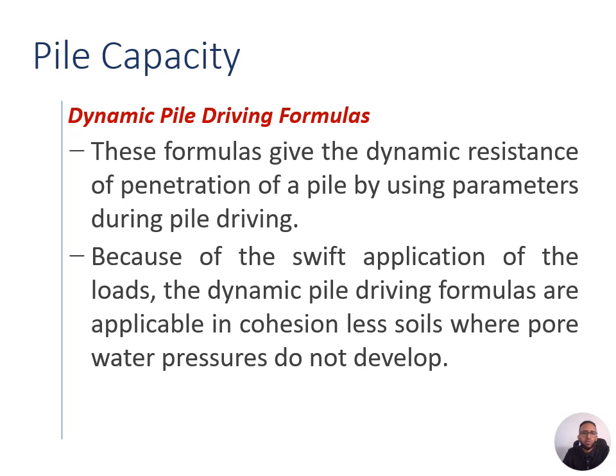The key advantage of dynamic formula is rapid application of loads, which makes them suitable for cohesionless soils where pore water pressure do not have time to develop. The formula takes into account factors such as hammer energy, pile weight, and the distance the pile is driven per blow to calculate the ultimate bearing capacity.